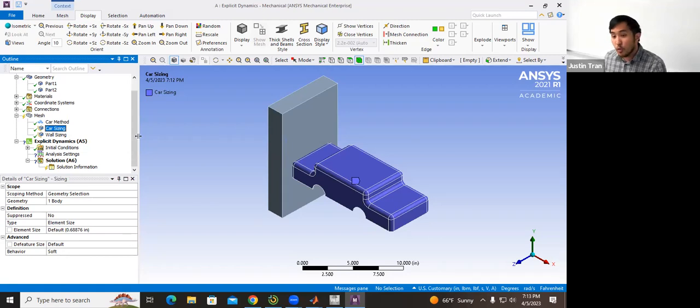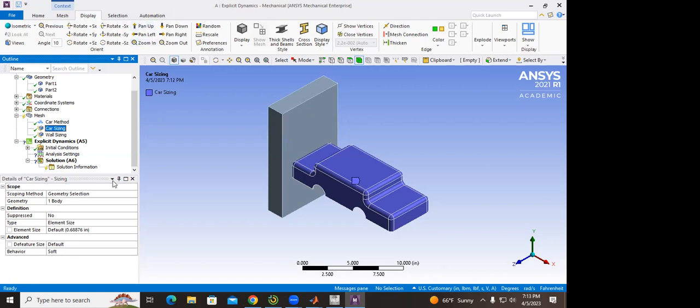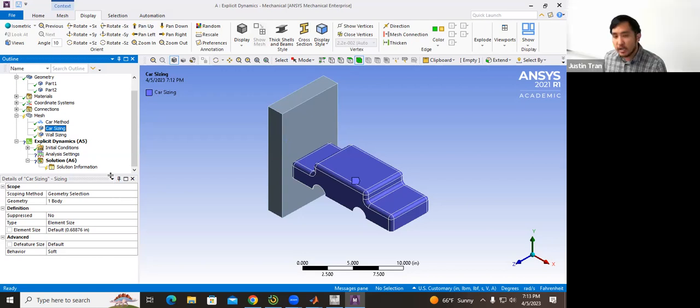I don't think I require it in this activity, but for a situation like this, you really want to run a mesh convergence test so that you can show that your mesh is good. Sounds good. And we're not using quadratic elements because there's an error in ANSYS. Exactly. ANSYS basically prevents it to limit the costs.